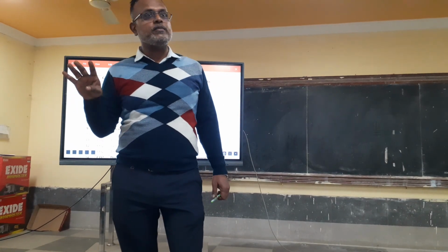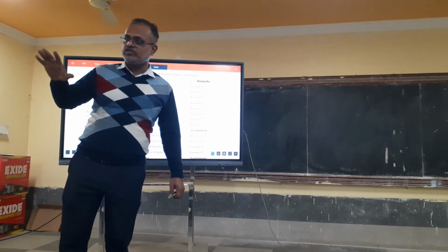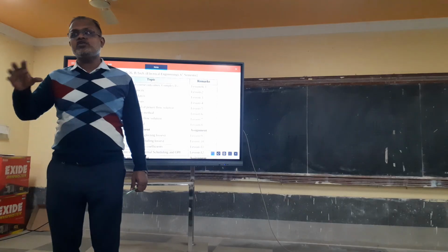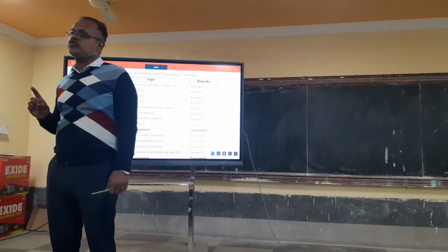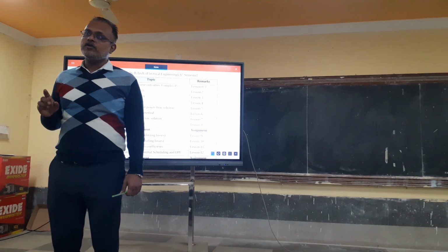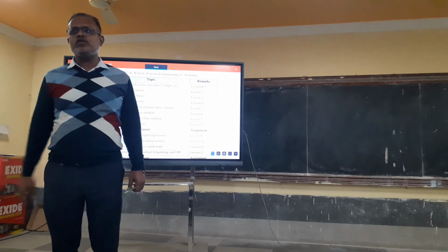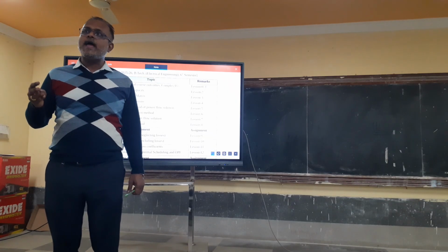So 4 classes we have discussed about transmission capacity, complex power and power flow equations. The rest of module 1, 4 classes, we will discuss about the solution of the power flow equations. One class we will devote to the easiest method, the Gauss-Seidel method. Then 2 classes on Newton-Raphson method, which is the most widely used. And finally the last class will be on fast decoupled method, which is the approximate method.